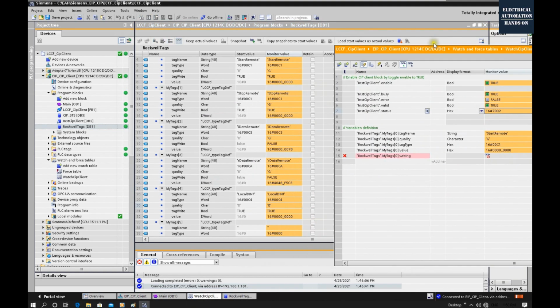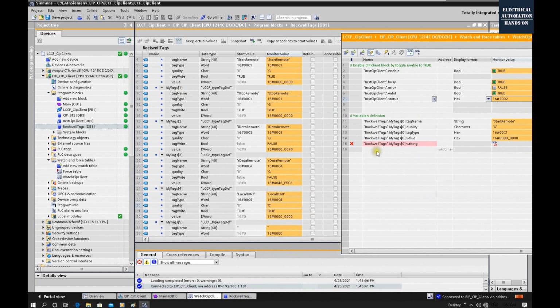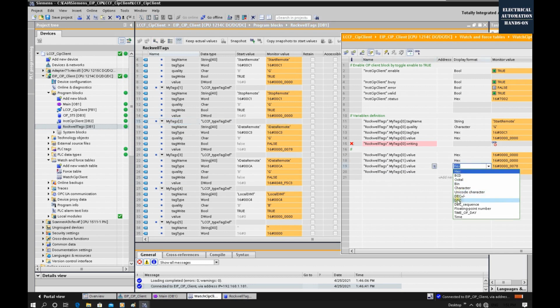All right, let me drag some tag variables here. To specially set or read the data, I will drag this value line to here. This is the full data. And this number 2 tag is the integer data, so I will shift the display format to decimal. And this index number 3 is the real value, so I will shift the display format to float. We can see it's reading data correctly, 120 and 3.14.